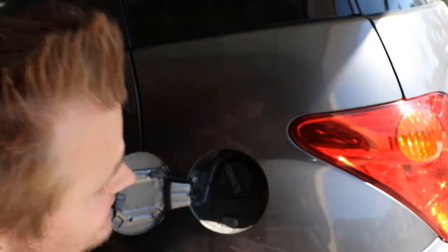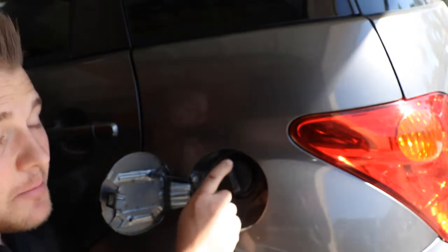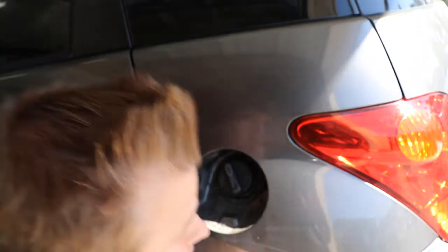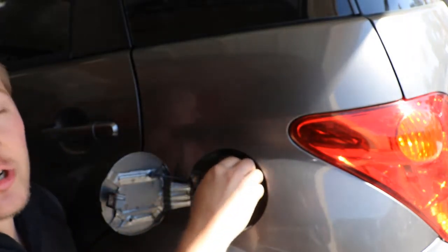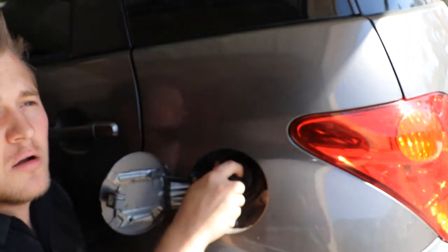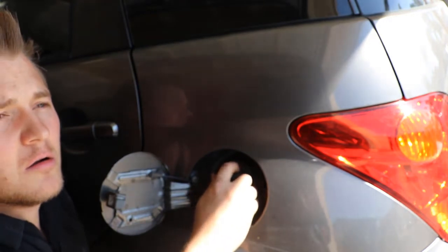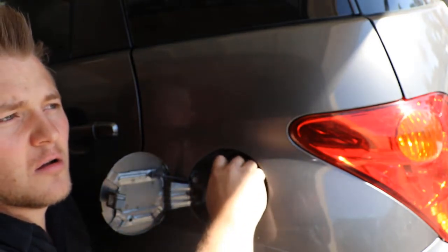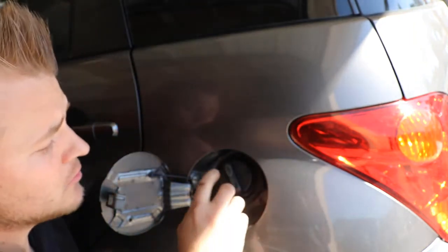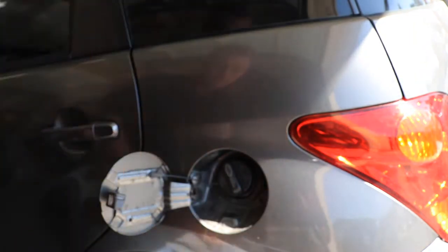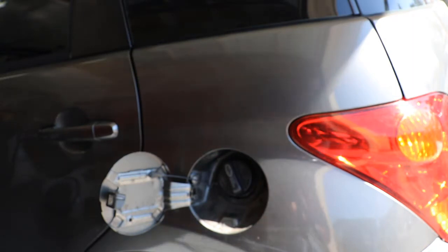I do hear a light hiss, but it may not be because the gas cap is bad necessarily, but because I put a little bit of higher pressure than recommended. Another way you can tell is if you start to loosen the gas cap, you should start to hear air escaping. There, I don't know if you can hear that, but it started to, which means the system is holding pressure. So, which is good. The gas cap is holding back the amount of pressure.